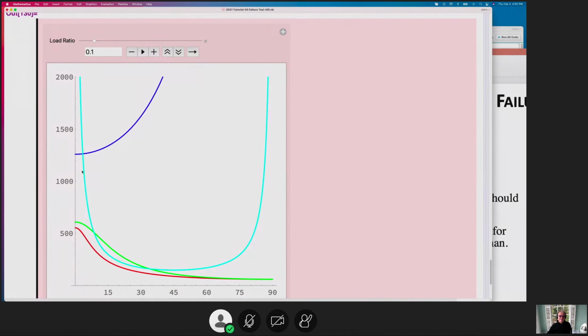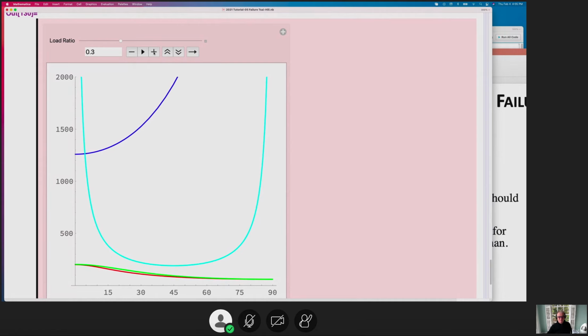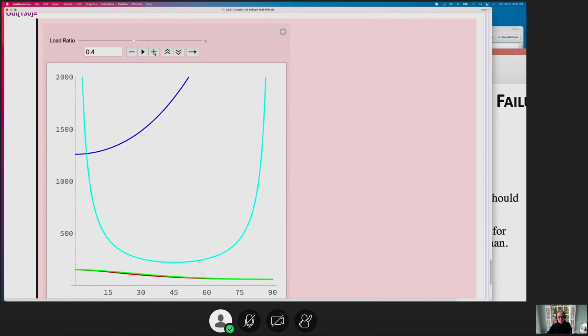How irrelevant this becomes. So these two mean nothing. This one, transverse, is starting to control almost right away. So even with 0.05, transverse failure is taking effect. And as I increase this ratio for biaxial, transverse failure completely overtakes, and fiber failure and shear failure have no influence as I increase my alpha.